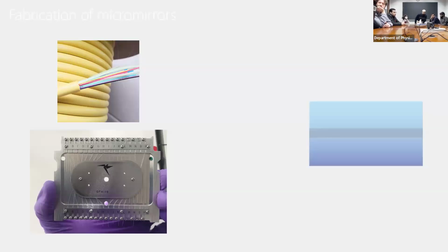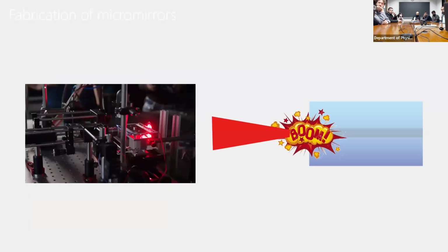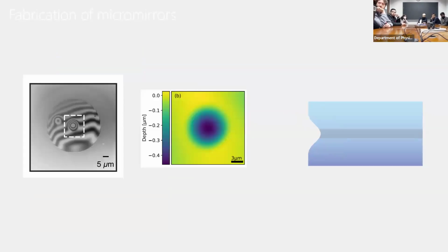Well, optical fibers, as you know, are used widely in the world right now for telecommunication and other applications. Colibri takes certain optical fibers according to the requirement, and then we cut them, we cleave them, what is called cleaving. We make the end of the fiber really, really flat. And then we shine a very high-powered laser onto the end facet to evaporate away the material. The goal is to make these concavities at the end facet that should look something like this on a white light interferometer, or if you want to see a 2D depth map, then you can also see it like this.